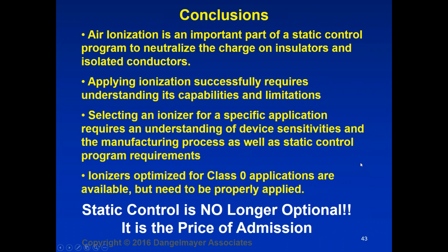So our conclusion here is, first of all, air ionization is an important part of the static control program. It's there to neutralize the charge on the insulators and isolated conductors, not on the people. It is a CDM issue. We want to get the charge off the essential insulator that's part of the product itself. Applying ionization successfully does require an understanding of its capabilities and limitations.